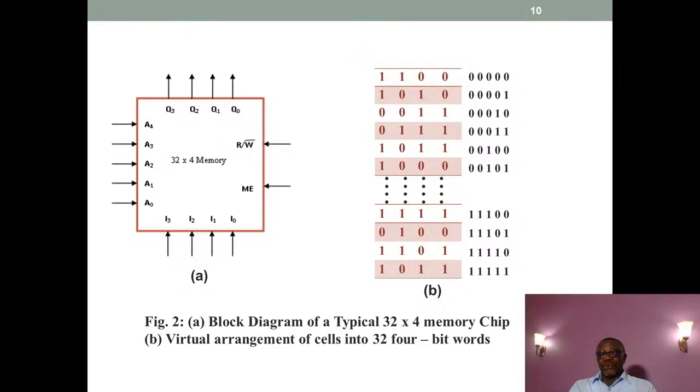Now, as we go on, we will see how this data can be read or pushed back to the memory. So we see this last one, which is location 11111. We can represent it in hexadecimal numbers, because if the address locations start getting lengthy, it becomes difficult to keep calling 11111111. So you change them to hex numbers. This last one, 11111, can easily be changed to its hexadecimal equivalent by grouping in 4s, starting from the right-hand side, which is the least significant bit.